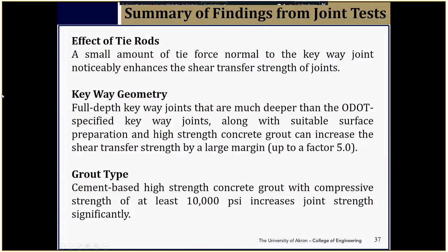So one of the first things we understood was the effect of tie rods. Tie rods are very important. At the same time, the tie rods we use currently in our specification may not be providing adequate clamping force. The keyway geometry is very crucial.